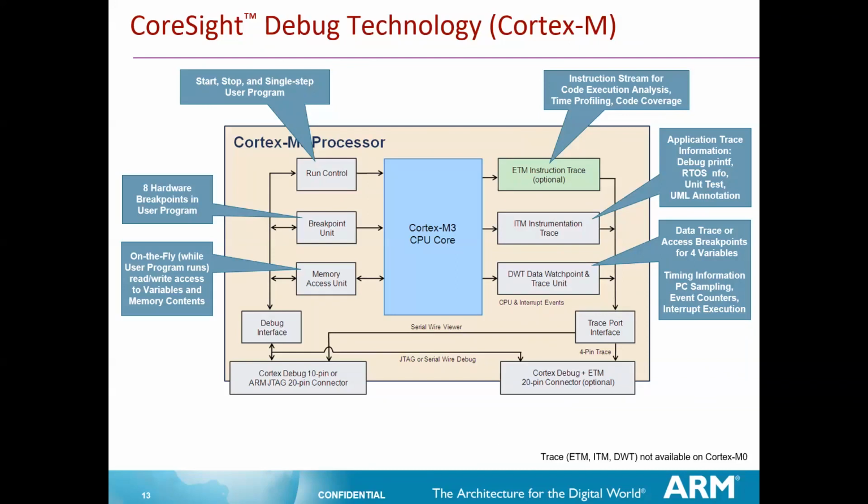At the time of debugging only, this particular block will be useful for you. If you're not debugging and you're running freestyle, like just programming the flash and powering it off, ITM is not even going to come into the picture. So in that way, your purpose of debugging is served and the UART is also safe.